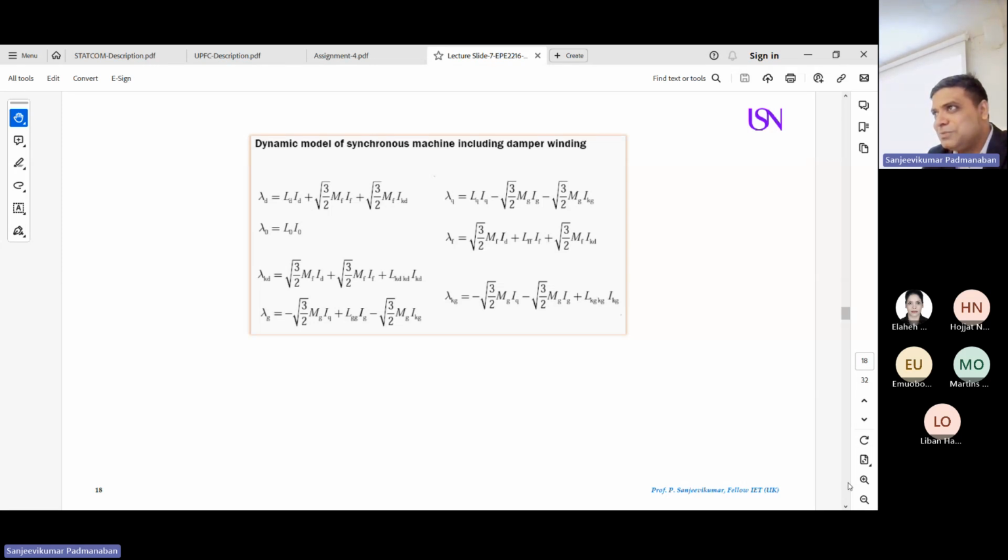Why? A synchronous machine is like a DC machine. You run your synchronous machine at synchronous speed, whereas in an induction machine this does not happen. We can have a damper winding in an induction machine, but for huge, high speed machines, we never use a damper winding effectively in the induction machine because armature reaction is very limited, near to zero. But in the case of a synchronous machine, we have armature reaction because you apply a DC excitation to your field winding. So its behavior is like a DC machine. In order to overcome that, we use a damper winding.